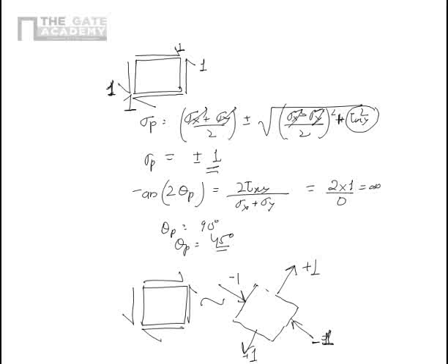Now, if this was designed without considering the normal stress, then the design would have been a disaster. This is a very good problem to see because it clears a lot of fundamentals. This problem shows that if there is only a pure shear condition, then about 45 degrees there is a pure normal condition, which means that the shear stresses vanish at a 45 degree orientation from the current direction.